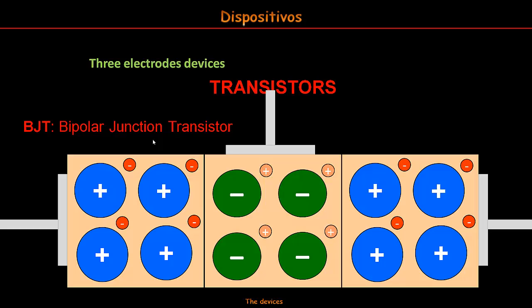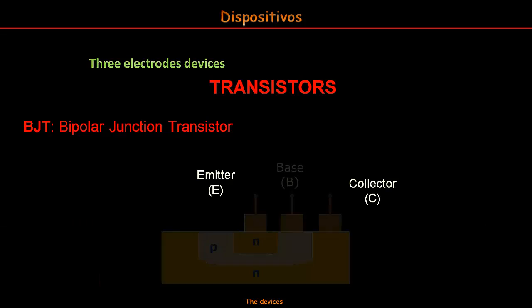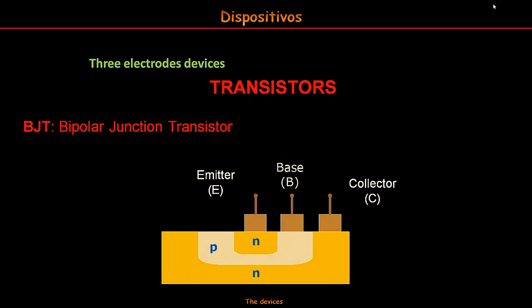This is not the real way to create a transistor. One doesn't glue two or three pieces of different types of semiconductor materials together in the hope of creating the junctions. The real way is to take a silicon wafer and get it doped to obtain, for instance, an N-type wafer. Here it is.